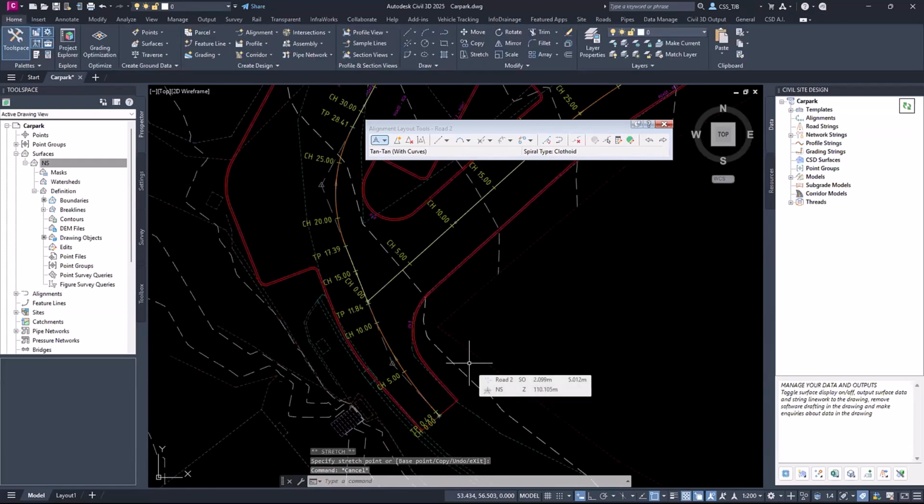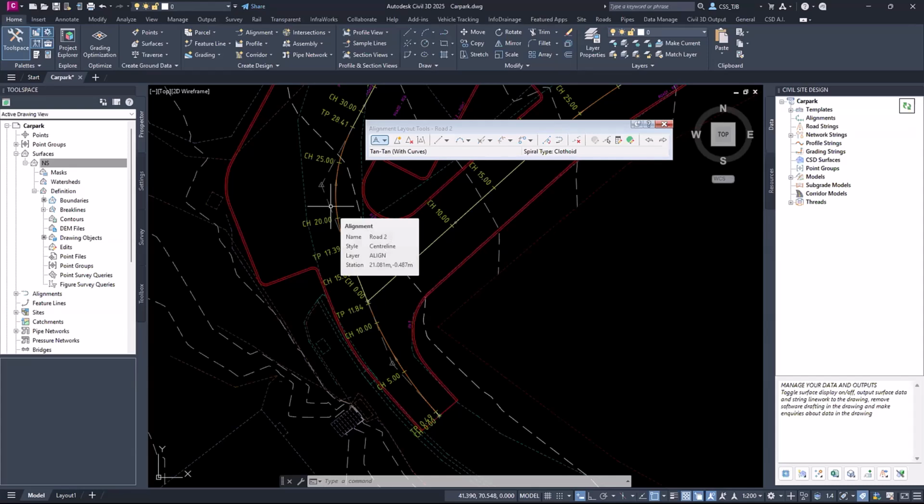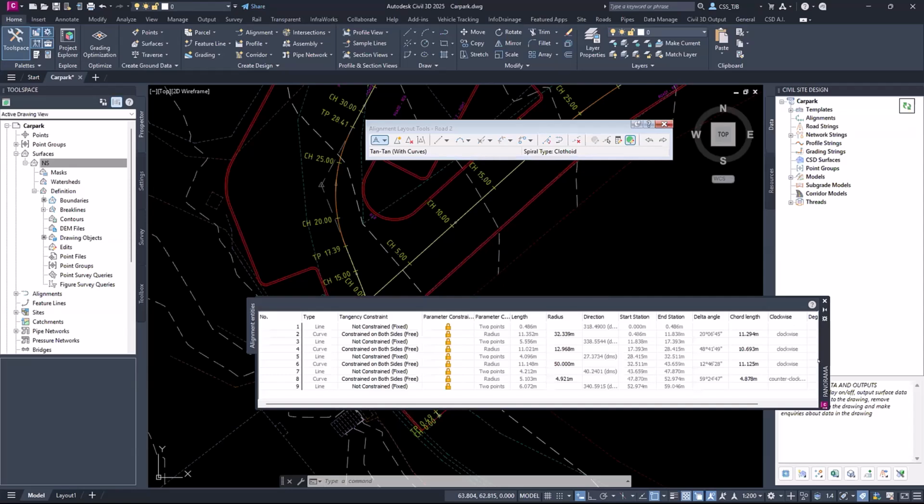So when you're doing some sort of reconstruction project, sometimes you don't start with the very beginning. Sometimes you go, oh, I need to fix or I need to lock in this radius. So this is that concept where you can just graphically fit things around and then manipulate everything else to go with it. That's where the layout tools really shine. You can also do numerical editing with this stuff.